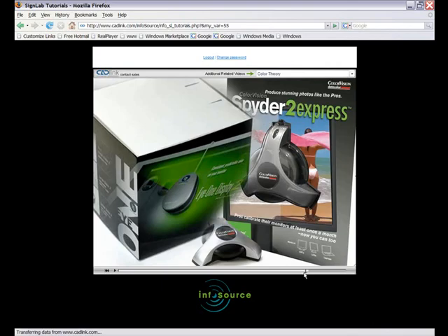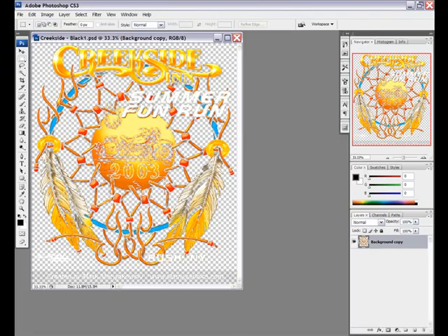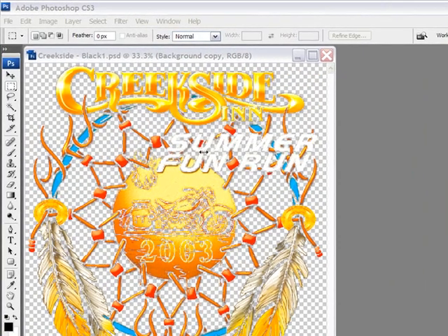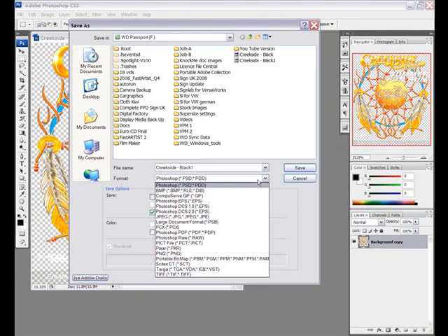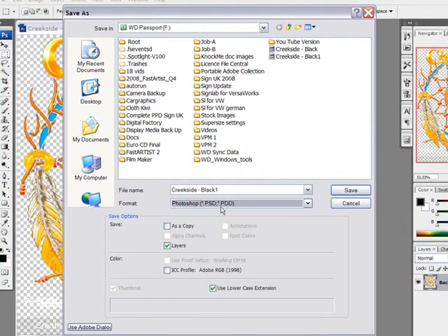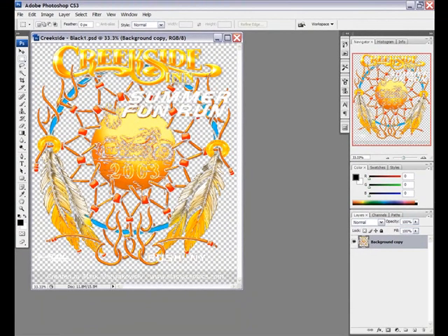Okay, so once you've finished with your images in Photoshop, you'll need to get them across to FastARTIST or FastRIP for production. You can't use the file print method to send images with transparency to FastARTIST or FastRIP, and this is because the Microsoft printing system and Photoshop doesn't support transparency in the file print method. So you must save your files as a PSD, TIFF or PNG and then import them into FastRIP or FastARTIST. If you need a more automated system of printing, it's possible to set up a hot folder in FastRIP and you can then save files into this area and they will be processed automatically.